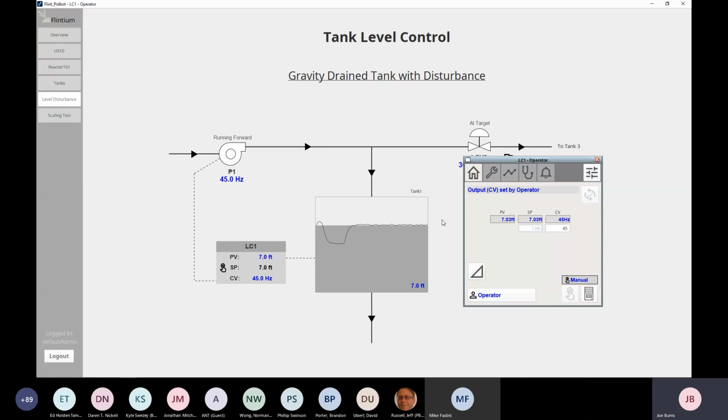Its performance is going to be significantly worse than if you had a sensor that gave you live information. But there are some more advanced techniques you can use to help with PID control. I'd recommend looking up what a Smith predictor does in that scenario to help net out the effects of that dead time. And whoever is asking the question is certainly welcome to get in contact with me after the presentation. We can talk about that more. Okay.